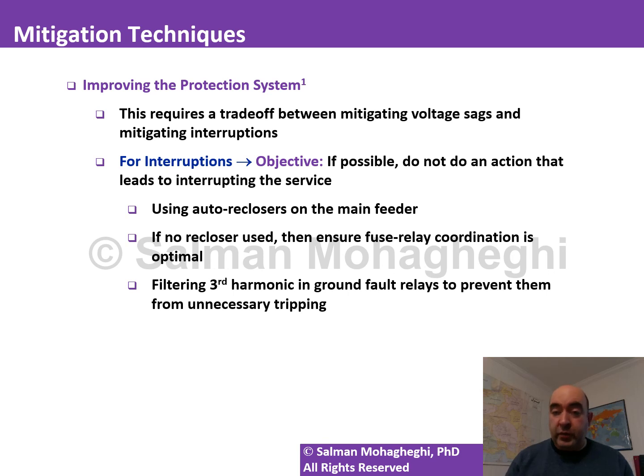If you don't have a recloser, you have to make sure that your fuse relay coordination is optimal, meaning that you have to make sure that the devices respond to the event in a way that leads to the least number of interruptions in the system. And of course, another technique would be to filter the third harmonic components in the system.